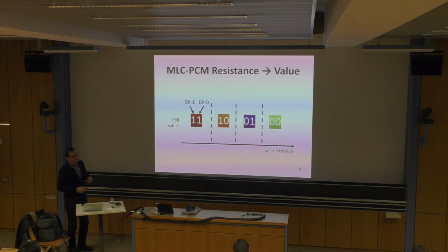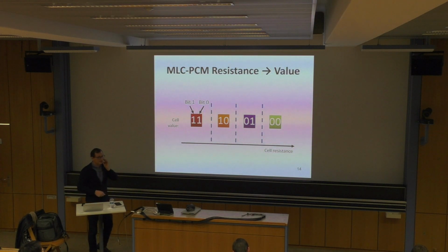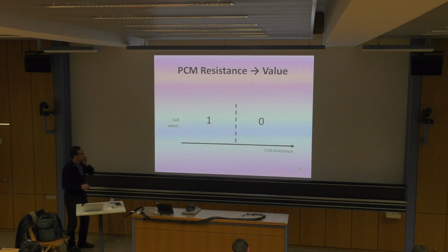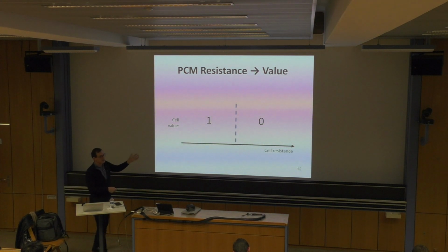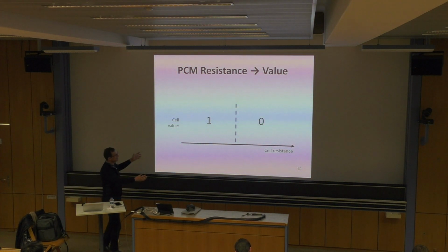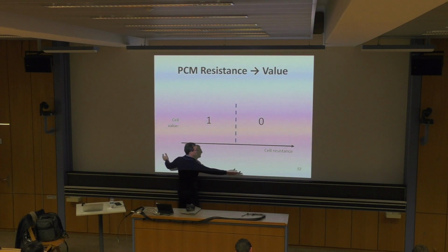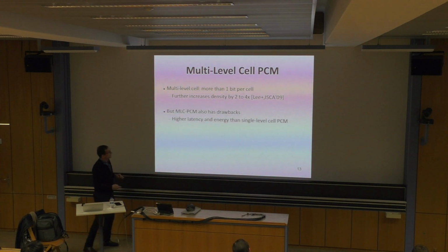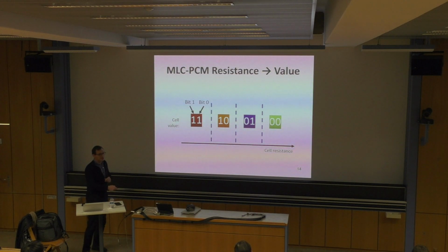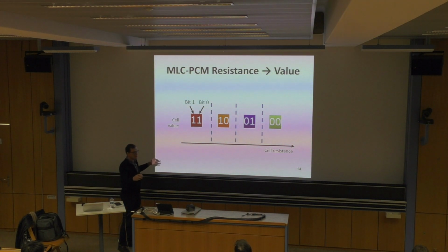Okay. So there are also other issues in MLC, multi-level cell PCM. If you go back over here, your noise margin is a lot higher here, right? If you store a single bit, single level cell. This is also called SLC PCM. SLC flash has the same thing, except in flash it's the voltage range over here. And if you encode more bits within the same resistance range, now your margins are much lower, right? Meaning, for some reason, if there is noise in your system, this resistance may drift to the right more easily. So you can get bit flipped more easily this way.